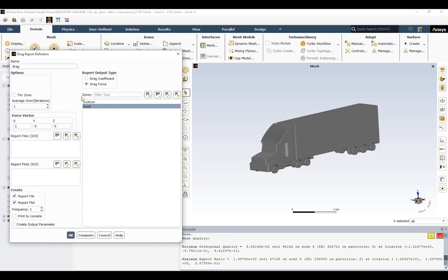So when you want to correctly calculate the drag force, you have to tell the software what the direction of the airflow is. In this case, by coincidence, the value that has been defined here is 1 for the X direction, while the Y and Z directions have the value of 0, indicating that the airflow is in the X direction and parallel to the X coordinate axis.